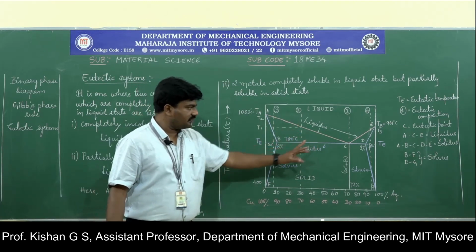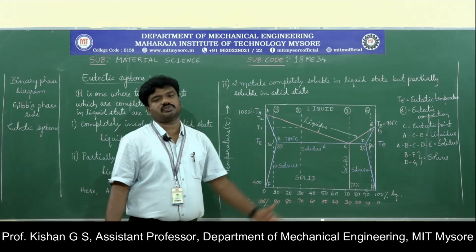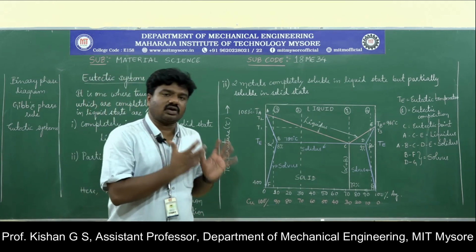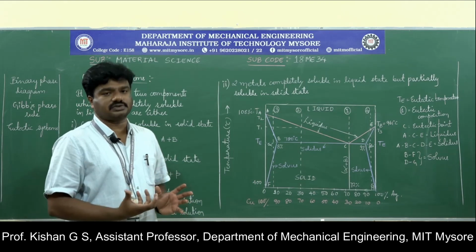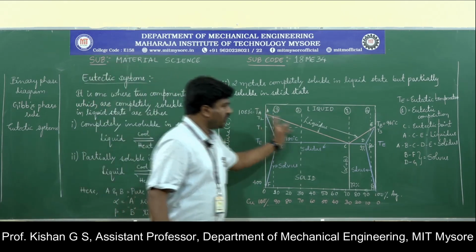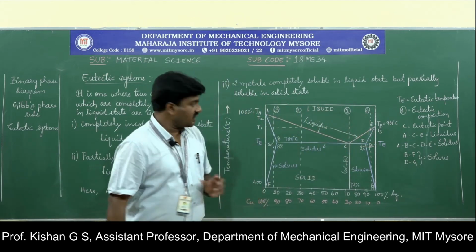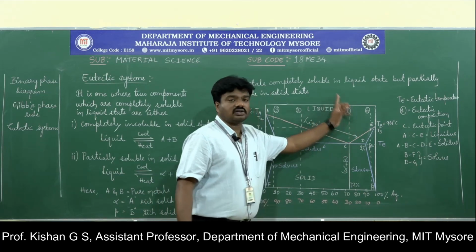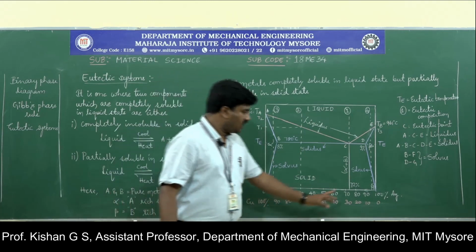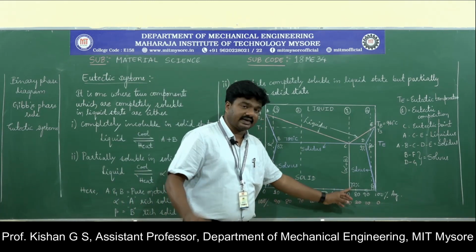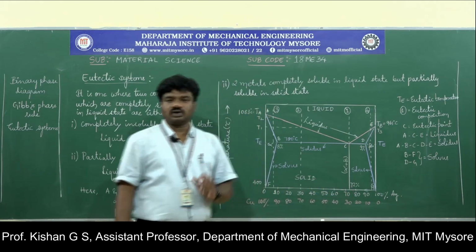So alpha represents the rich mixture of copper, whereas beta represents the rich mixture of silver. The main concept of understanding this diagram is to assess the behavior of various compositions. Here 1, 2, 3 and 4 are only the points of concentration, where we are going to check, whereas 1 is always the constant number, which represents the eutectic composition only. See, here it is not 70-30, it is the exact eutectic composition: 72% of silver and 28% of copper.